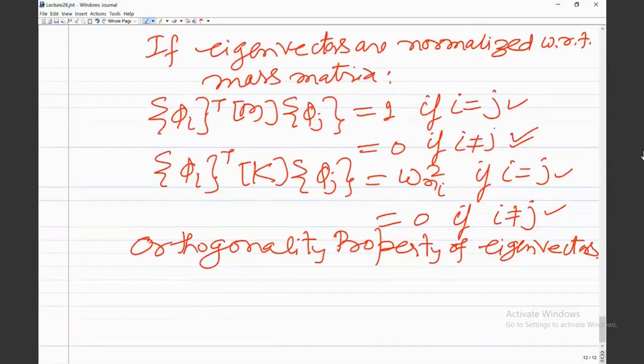If it is not a regular geometry, then you won't be able to discretize it into rectangular or square elements, but you have to fit arbitrary quadrilaterals. That is why we want an element which can fit into any arbitrary geometry in the physical coordinate space, and that is the need for an arbitrary quadrilateral element.